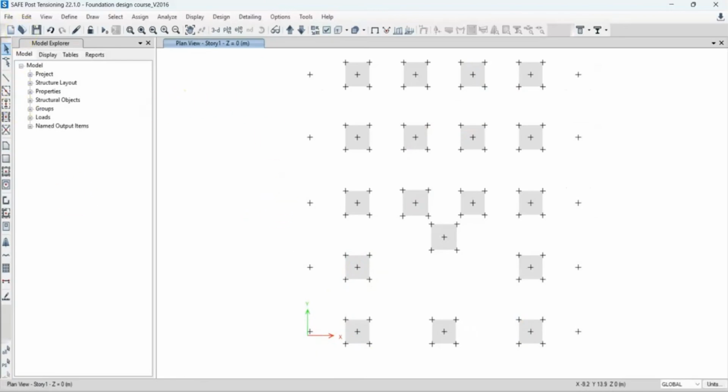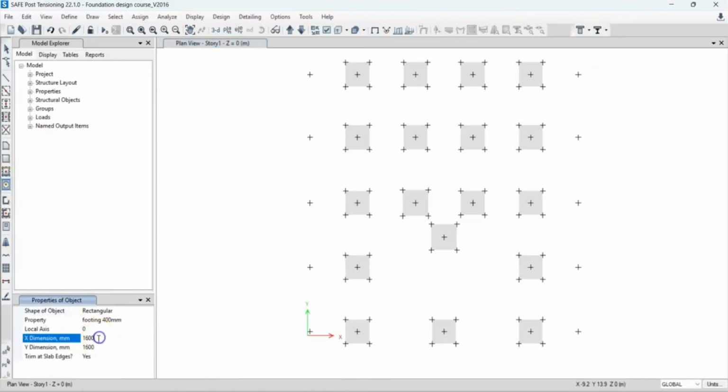Then I'm going to redraw the footing again. So click on draw quick points around the area. Instead of 1,500, let's go with 1,200. Or let's go to 1,000. Yeah, let's try 1,200 millimeter. So you simply click on this point, click on this point, this,